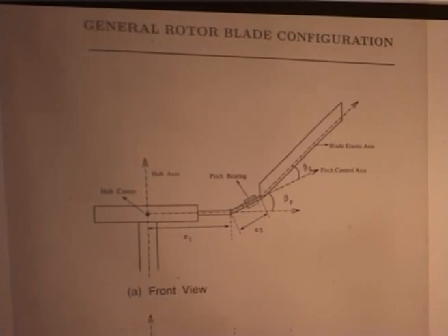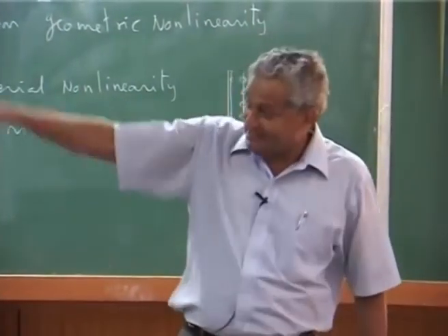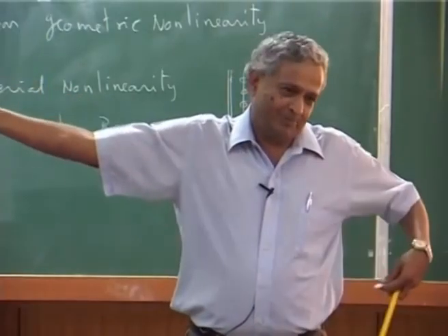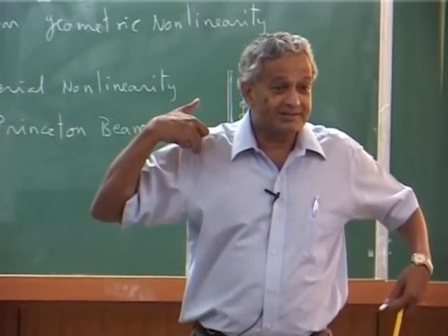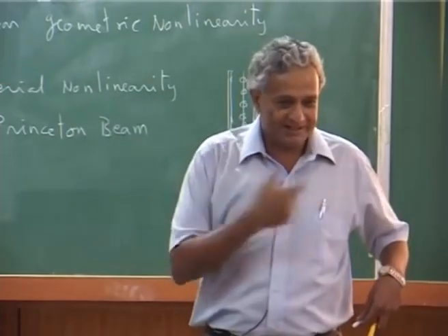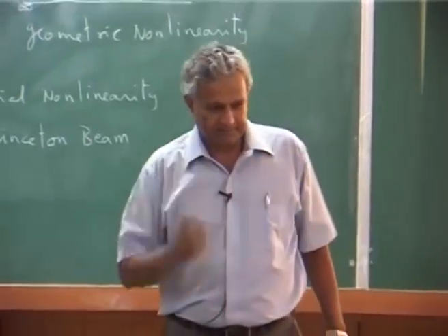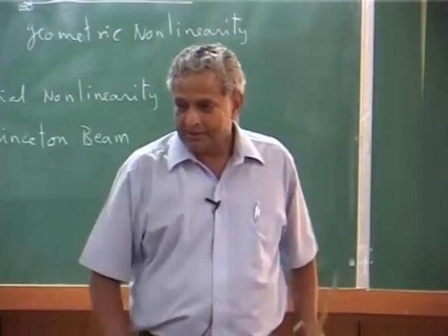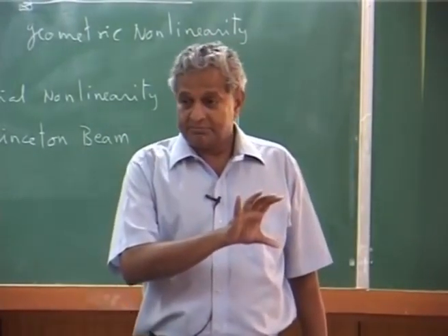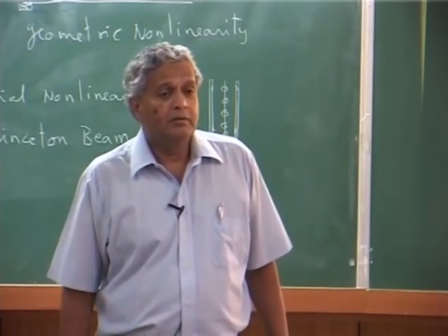See, what will happen is aerodynamic load tries to take it up, centrifugal load tries to bring it down, okay, and there is an equilibrium. Suppose if your rotor blade is already kept at the equilibrium angle, there is no root stress. You follow what I am saying? That is why that is given, that pre-cone, relieving root moment in the blade. Otherwise, you have to make the root section a little thicker. But it will also transfer as a moment to the flap hinge.